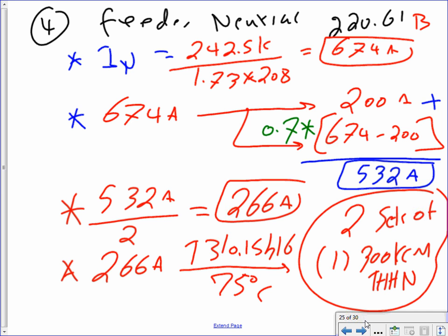Even if you went just a little bit over 225, we can push it to 300 amp panels. But if you start going higher than 300 amp panels, it's not a good idea. Do you guys know why? Because imagine these are lights. In order to have 300 amp at 208/120, that's a lot of lights. You're going to have a voltage drop problem pulling all these branch circuits from everywhere. It's like the two floors going to the same panel. What's the issue? There's nothing wrong with that except voltage drop. You start encountering a lot of voltage drop issues.